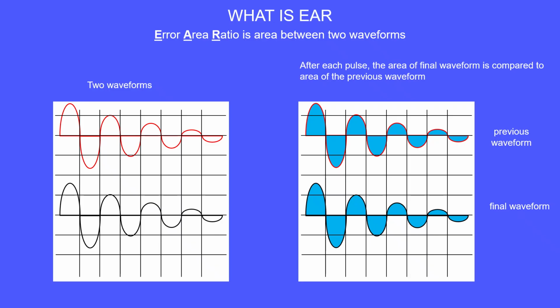Line to line surge is comparing waveforms between phases. This requires the rotor removed from the stator due to the rotor influence between phases. A pulse-to-pulse test compares waveforms of the same phase as voltage is increased. This is the test we perform in the mills because the rotor is installed. Rotor influence does not affect a pulse-to-pulse test result. A successful test is when the ringing frequency does not change throughout the test.